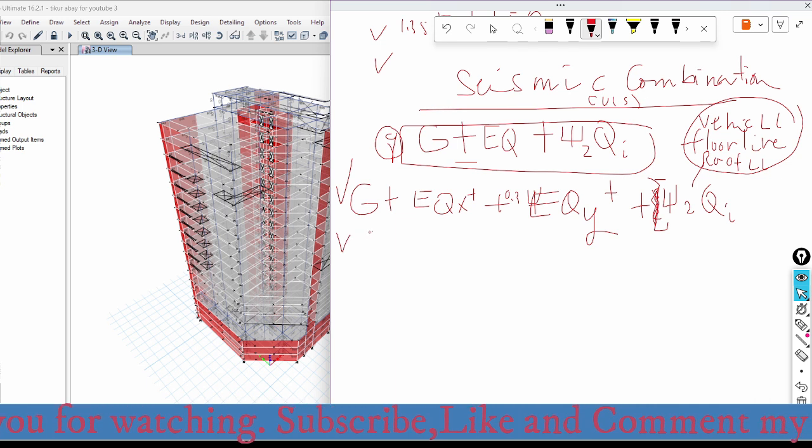And the second combination will be the permanent load plus 100% of the earthquake load in x positive direction, combined with 30% of the earthquake load in y direction, plus this one.